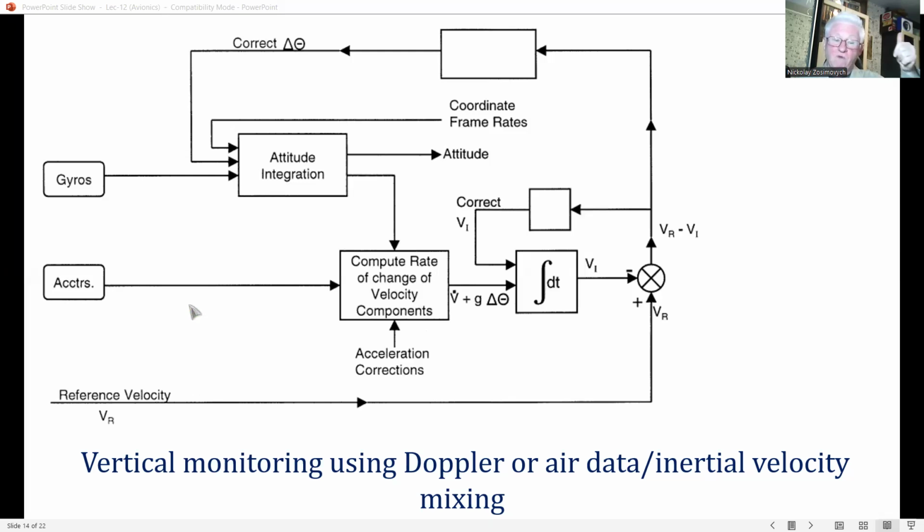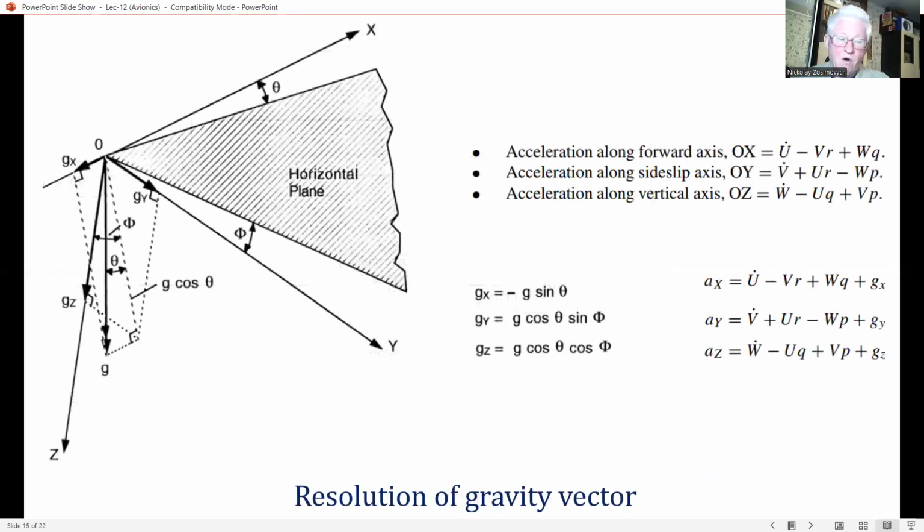A, the use of air data derived velocity as opposed to Doppler. B, the use of aircraft body axis as a reference frame of axis. And C, the application to a lower accuracy AHRS with lower cost gyros in the few degrees per hour bias uncertainty performance bracket. So, derivation of velocity component from the air data system.